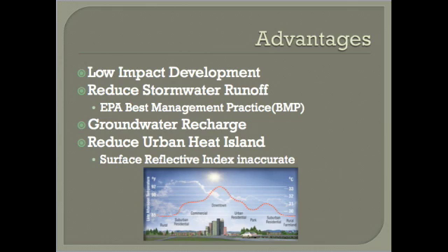This quality is measured by the surface reflective index. This index measures a test that shines light on the concrete and measures the reflectivity. A score of 29 certifies a surface as LEED certified. However, pervious doesn't score well on this test. The fact that it is multi-angular means that the light doesn't reflect back in the right place for measurement, so although we know it reduces the urban heat island, it is not yet LEED certified, although they are working to get it so.